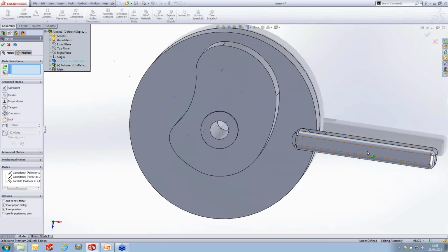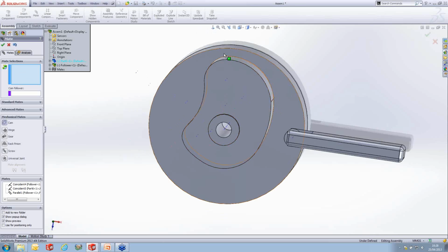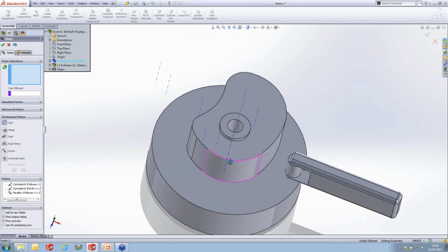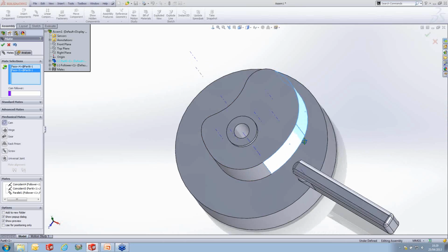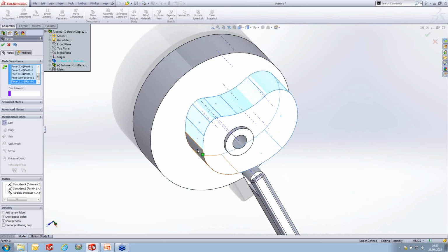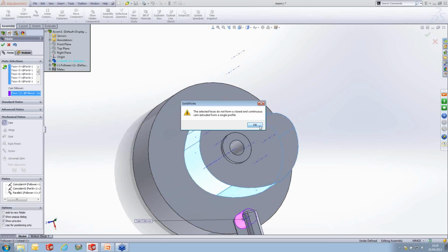And then the final mate is that cam mate. Now one thing to bear in mind here, to insert the cam mate, we select it from the mechanical mate section. You need to make sure that all of these faces are tangent, so you'd have to go into the design and insert some little fillets between the areas, because you'll probably find, if I select all the way around this cam, it will give me a bit of an error when I try to select the cam follower there. If you hit the tick, it will probably give me an issue. There we go. It needs to be continuous.